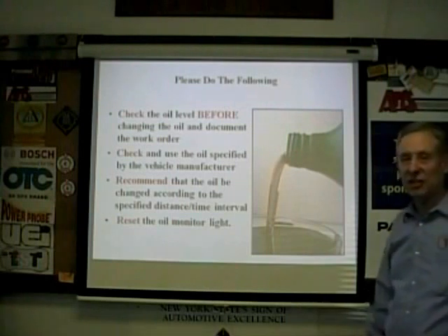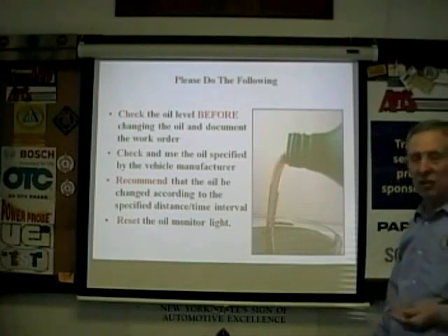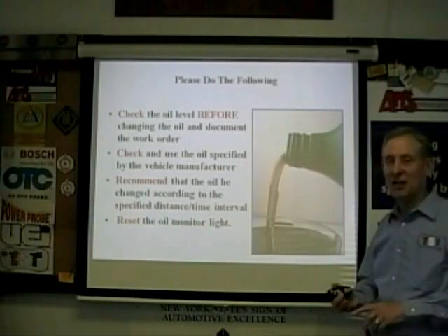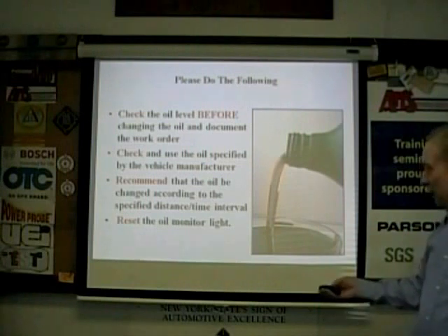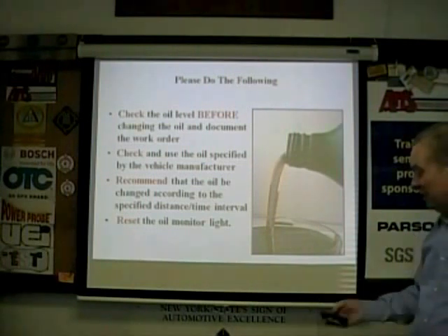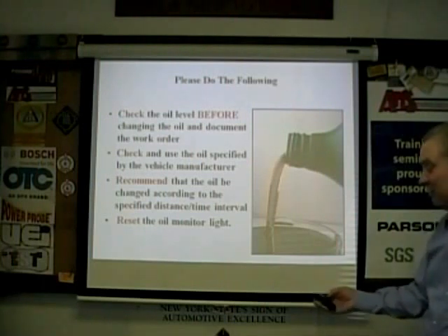They basically do a mass spectrometer test and look for different metals, different chemicals. They'll test viscosity and all of that stuff. And they'll reset that oil monitor light, so the customer knows to come in. And I like to put a sticker on the windshield. I'm old-fashioned that way. I don't put them on the door jamb because nobody looks at those.